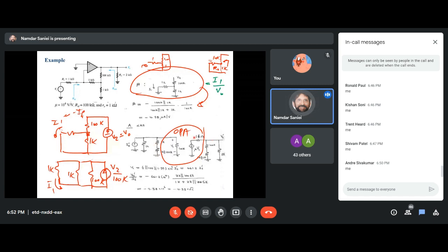Now, this is our amplifier, and this is the op-amp with output resistance, input resistance, and the gain, mu. We need to calculate V1, and V1 is nothing but this input current IS coming into the parallel combination of these branches. So these are the parallel combination times the input current, in kilo ohm. I mean, these are in kilo ohm times that current.